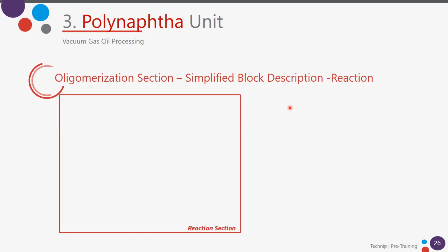But we will see later more about why we have 2 first reactors, okay? Because of course it will be the first reactor that will deactivate earlier than the other ones. But they have designed it so that you can regenerate this first reactor catalyst only, okay? While in operation during normal operation, okay? But we will see it now in the process description.